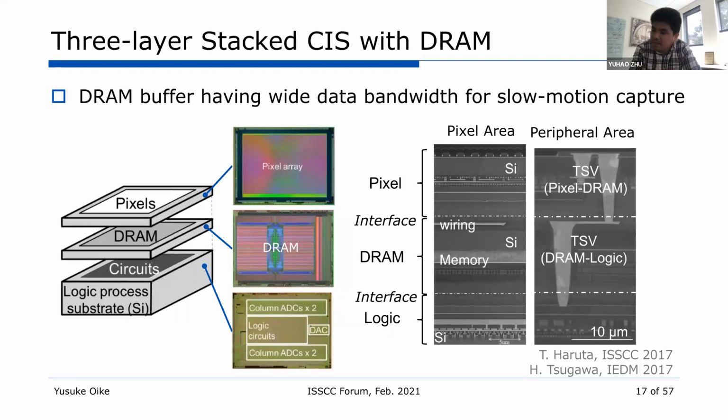Sorry, I was going to say that actually there are foveated image sensors, where the pixel layout is non-uniform, so you can have denser pixels in the middle of the pixel array, and sparser, maybe even larger pixels in the periphery. So you can even specialize and customize image sensors to exploit this foveation. And I think those are also incredibly interesting.